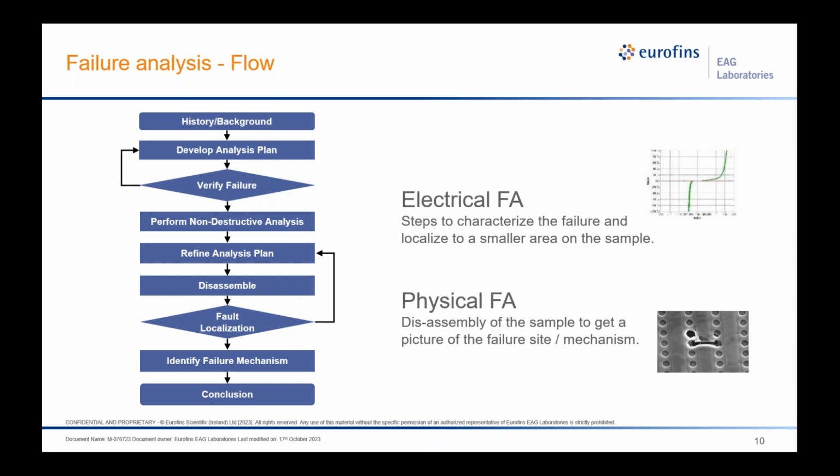Sometimes customers will engage us and ask us for a project, and we'll actually give them some of these initial questions, like what's the sample type, what's the failure mode, and some of the history, like where's the failure origin, failure rate. All of these actually tell a story. And we always in FA like to get back and try to answer that story with the findings that we have. So it starts with gathering information, failure mode information, background, origin of the failure. And then we start to put together a rough analysis plan in this first phase.